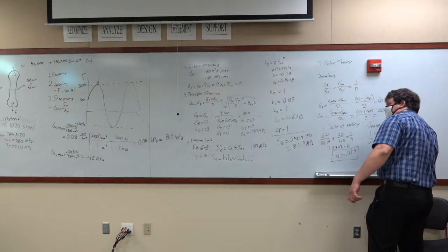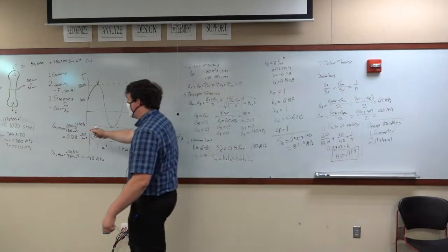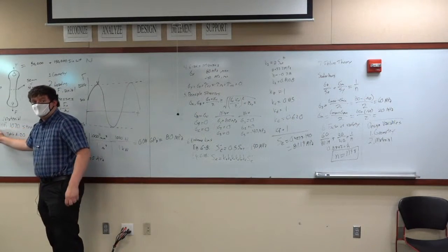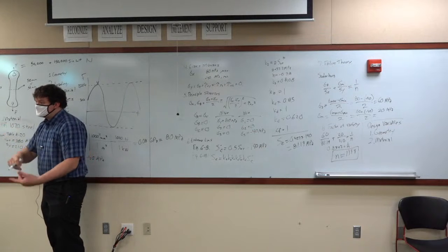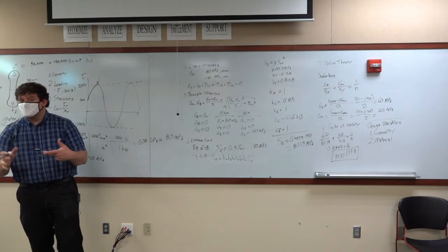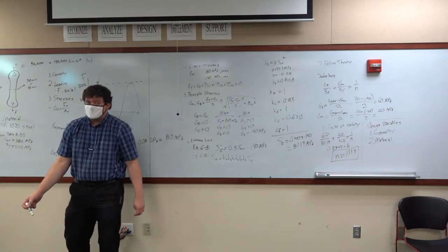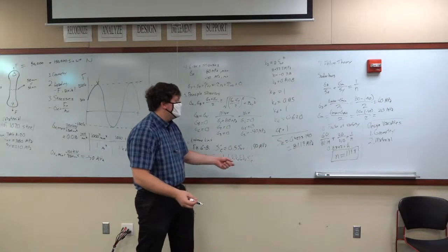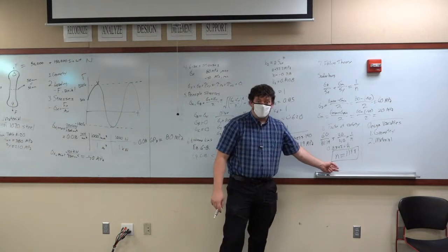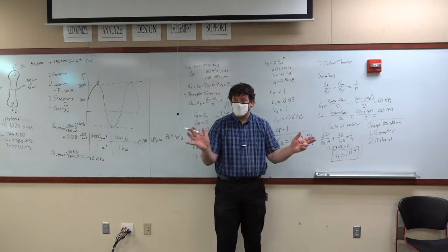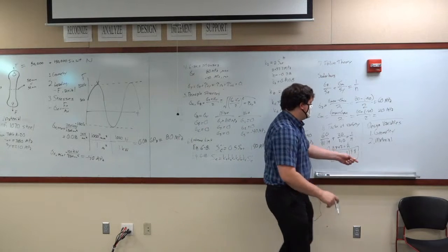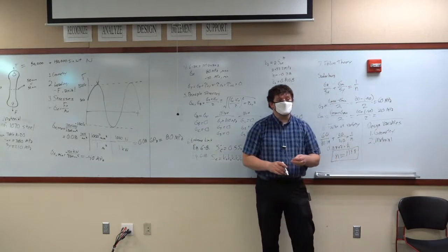And that can be as simple as saying, hey, we're not going to be using hot rolled, we're going to be using cold drawn. Same material type, different treatment. Okay? Different type of the way that it's configured. That can be all it is. As soon as we do that, this factor of safety would go over 2. Just FYI. Now, what are the other 2 design variables?